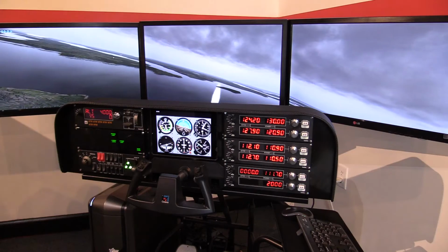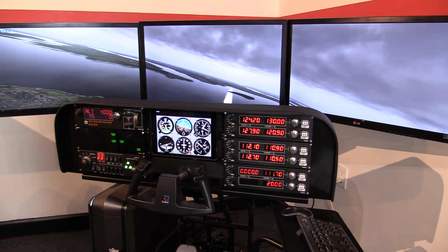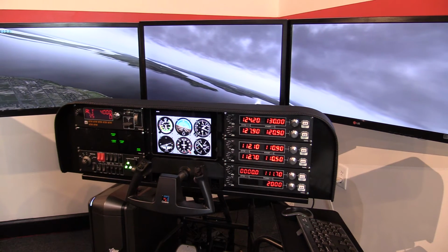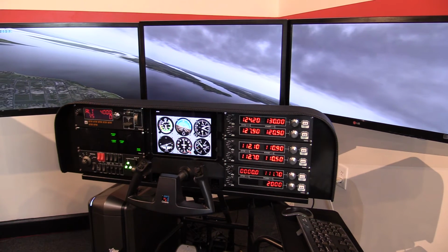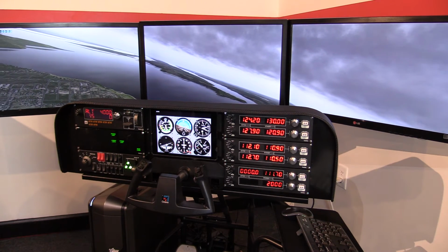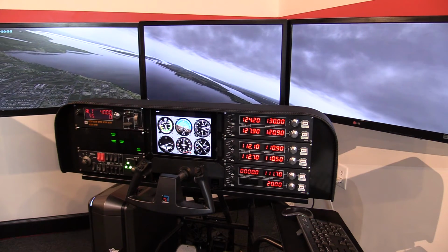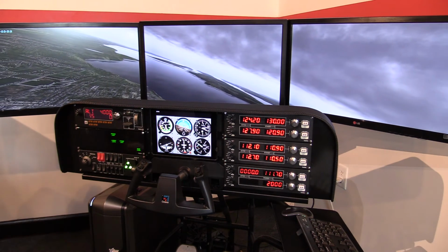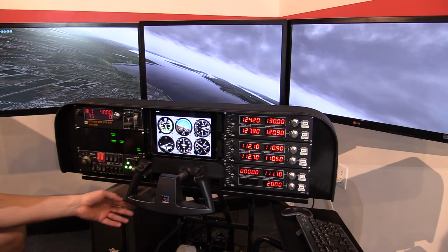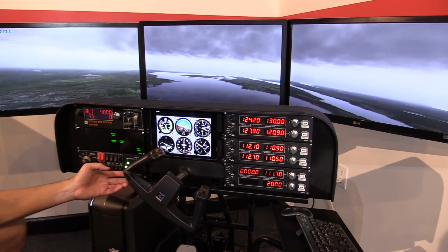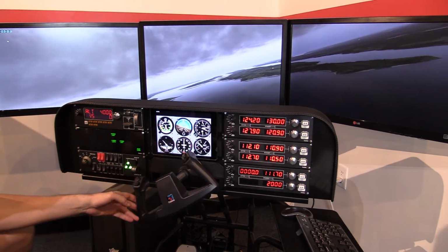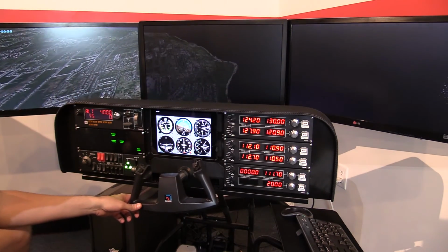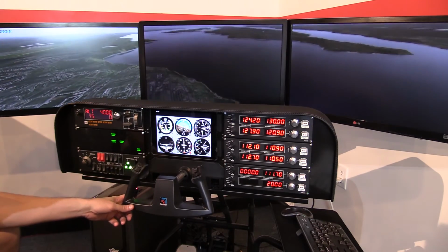Hey, so now we're going to fail some stuff. Alright, so let's make the airspeed indicator inoperative, the artificial horizon inoperative, and the altimeter inoperative. Initially you may not be alarmed because it doesn't look like anything's wrong. But if you pay attention, our artificial horizon is no longer changing. And I'm going to push the nose down here. Look, our airspeed's not going up, and our altimeter's not changing.